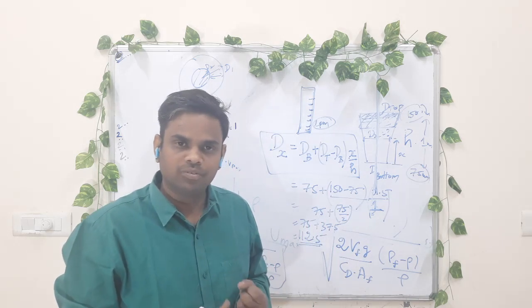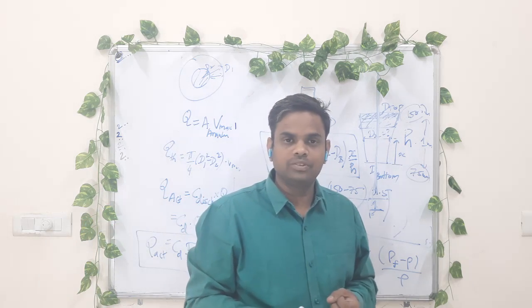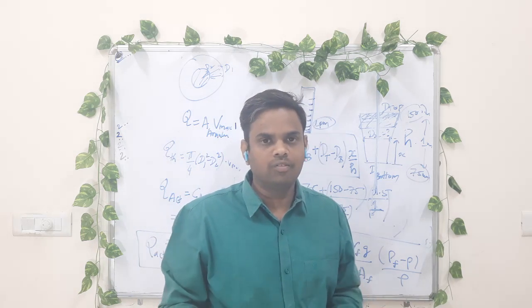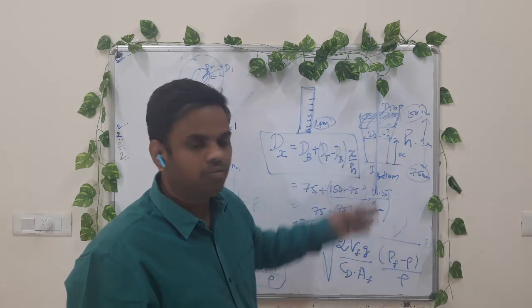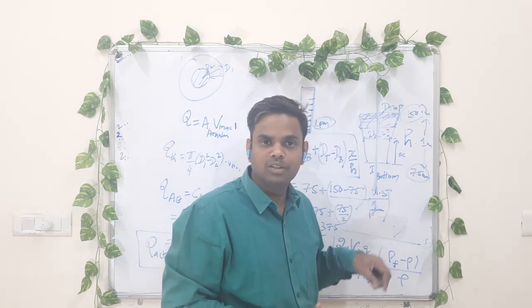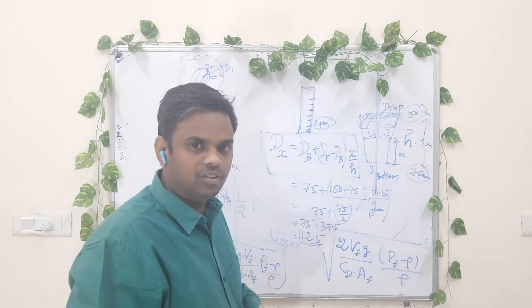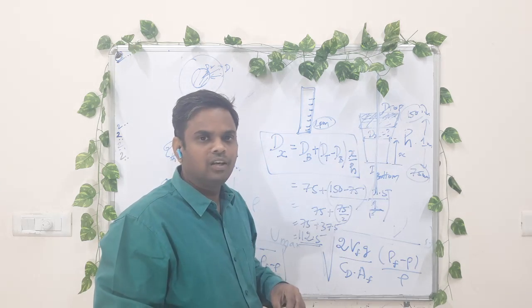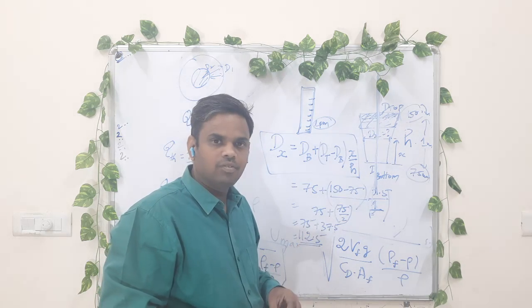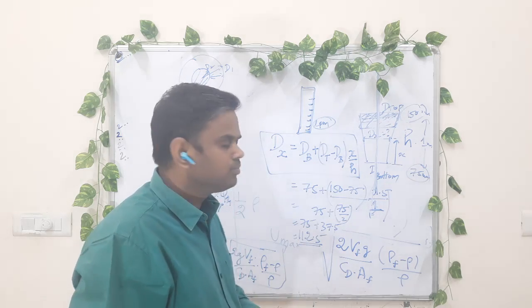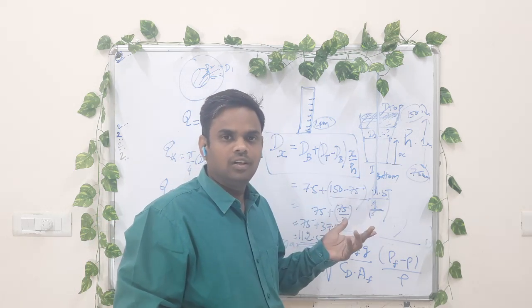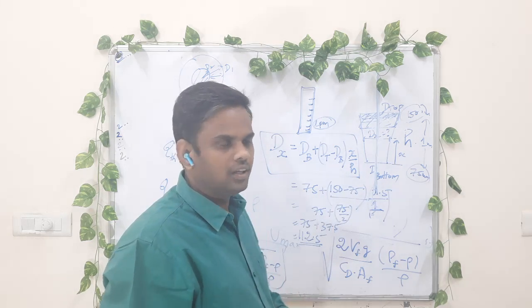That's why it is usually made of stainless steel. It can even be made of ceramics, bronze, monel, or aluminium. Different types of float materials are preferred depending upon the fluid we are using. That is one advantage, but the only limitation is that the float material may need to be replaced if it undergoes corrosion. If a corrosion-resistant material is chosen, that problem can be addressed.